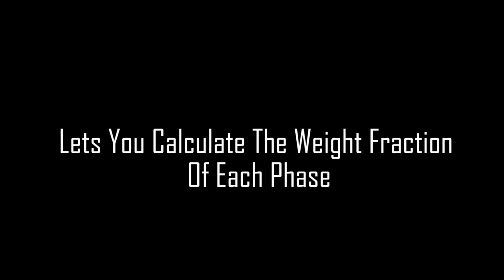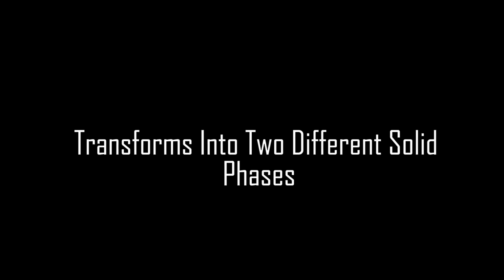It lets you calculate the weight fraction of each phase present. Clever analogy. You mentioned eutectic, liquid to 2 solids. Are there solid to solid transformations too? Yes, eutectoid reactions. Similar idea, but one solid phase transforms into 2 different solid phases upon cooling.